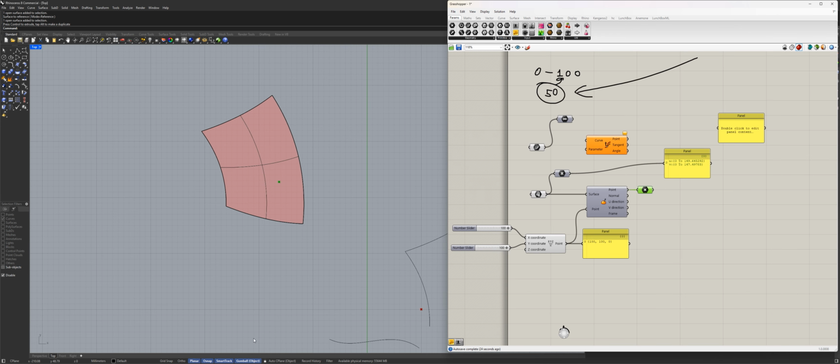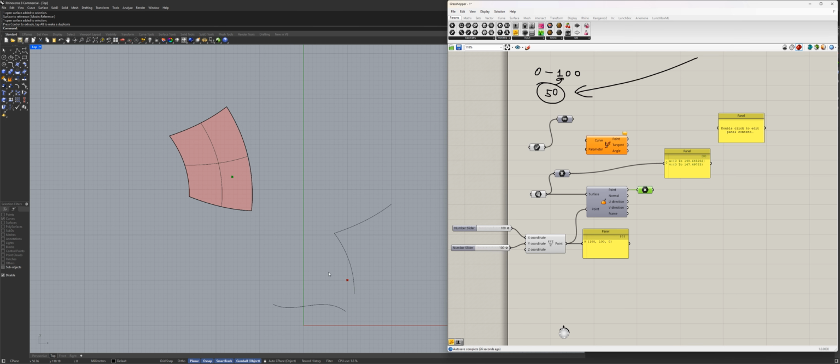All right. So if you think about that again, this is actually amazing, because what we did is we took a coordinate in Cartesian coordinate space and were able to map it, or visualize it, on a mapped surface using its domain. And now we have the representation of this point on a surface, right? And this is relative. So if I construct not 1 point, but 2 points, or 3 points, or 4 points, or a grid of points, which has a very specific relationship between each other, and use them as my points,